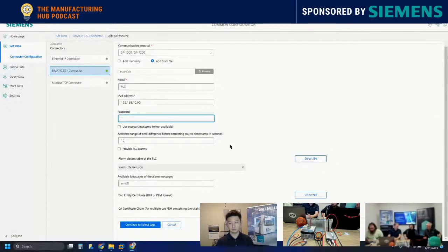So I'm not going to pull every data point out of a PLC every scan of the PLC. I'm only going to pull that data that has been changed, and I'm going to do it at that polling rate of, is it 100 milliseconds, half a second, 1 second, 5 seconds, 10 seconds. Interesting. I like that.